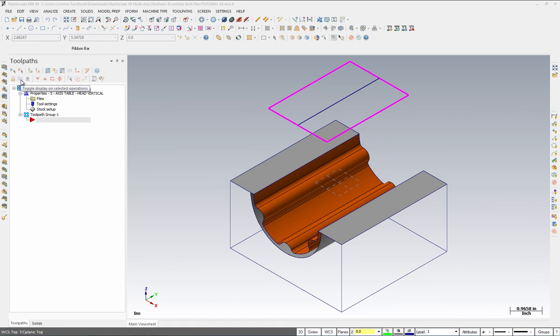For the first step, we're going to do a multi-surface 5-axis toolpath which uses a set of offset pattern surfaces called a cut pattern to control the tool axis normal to it. Next, the toolpath compensates the tool tip selected compensation surfaces. Tool axis vectors can be modified to initiate or terminate through points, stay perpendicular to the plane, stay normal to pattern surfaces, or follow an open or closed chain of curves.